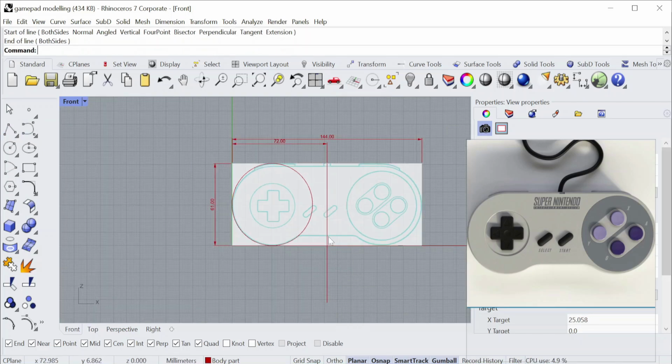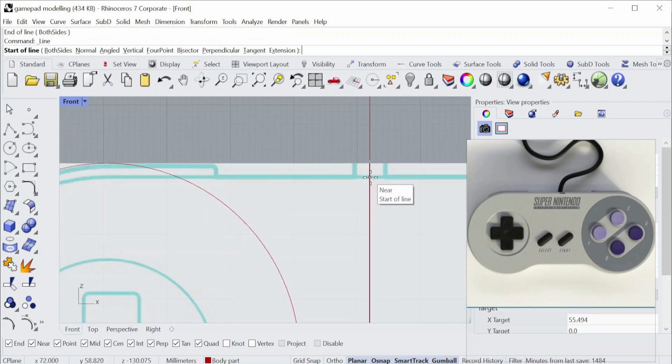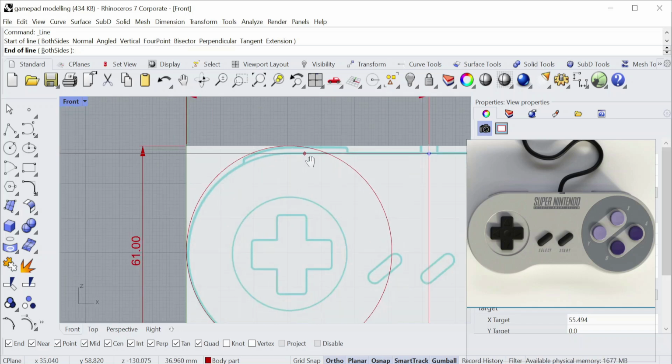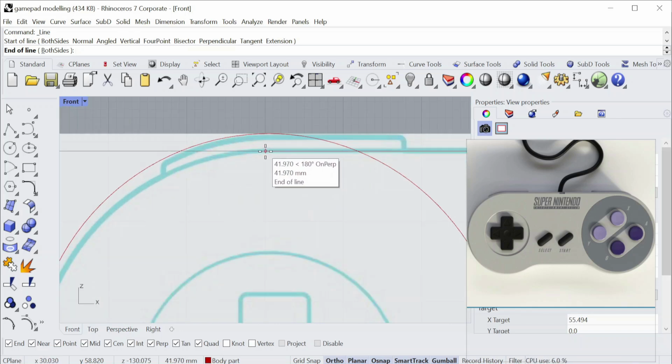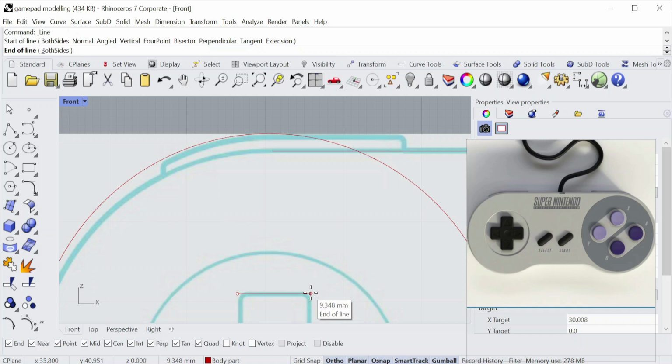In the next parts of the video, we will complete a complex 3D geometry modeling by applying commands such as Boolean differences, wirecut, fillet edge. To summarize, we draw a circle with a diameter of 61 millimeters. Take the midpoint of the 144 millimeter line as a reference and reflect it with the mirror command.